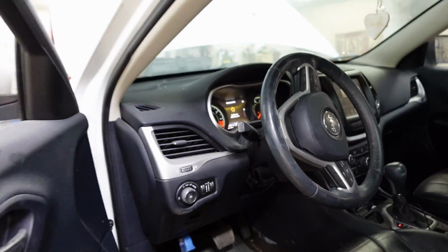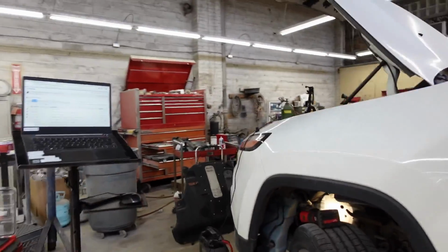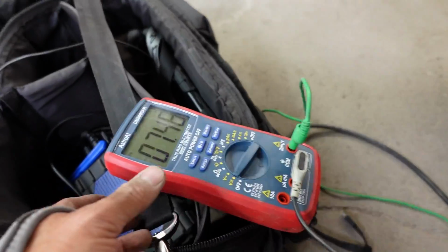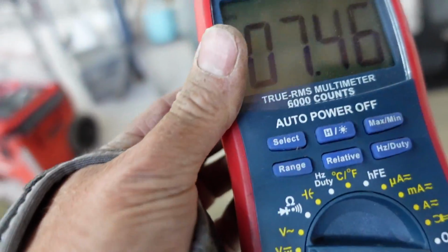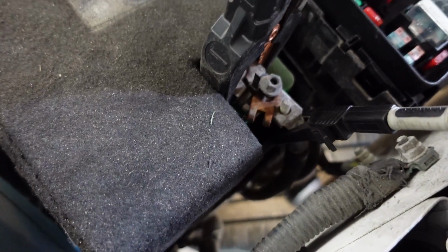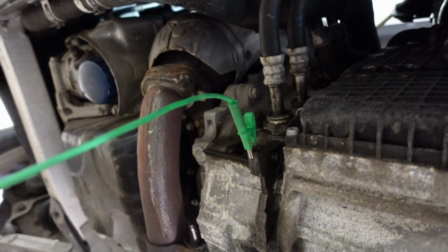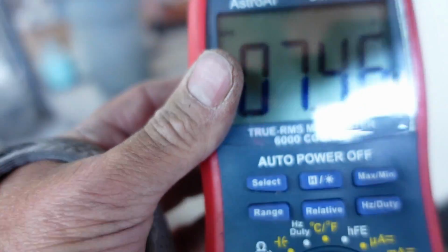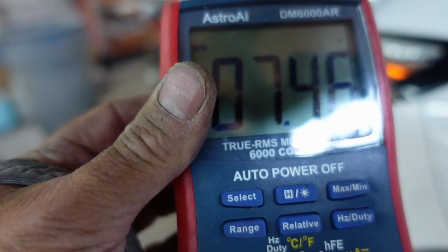So let's take a look at something. I want to show you that, once again, that code is active. Here is my multimeter. Okay, we've got 7.4 volts on our multimeter reading between battery negative right here. I'm clipped on the battery negative cable down there, and then I'm on the transmission itself over here. I'm clipped onto the transmission part of the bell housing just so we have a connection. Guys, we should never ever have 7.4 volts on our ground circuit.